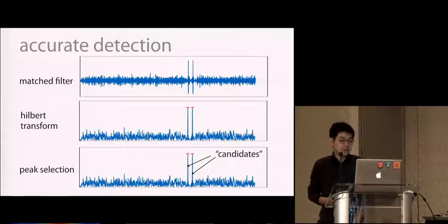But even after this, we still get multiple peaks because of the multipath issue and also some echo noise. So picking the right peak is very important. We defer the decision-making until after our payload decoding. If the decoder fails, we reject this peak. In most cases, after the decoding, we will only have 1 peak.